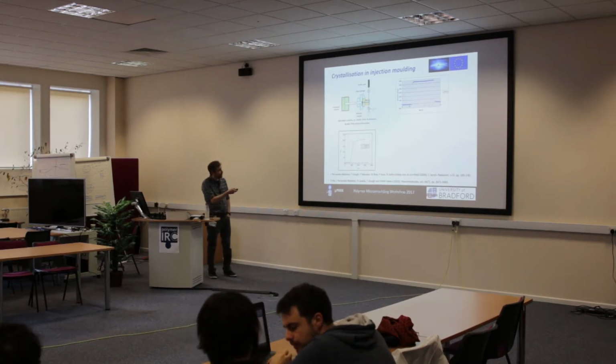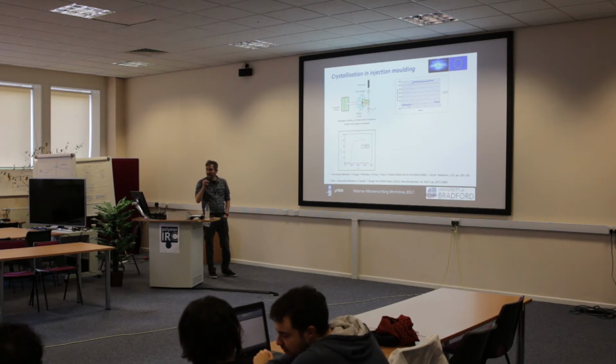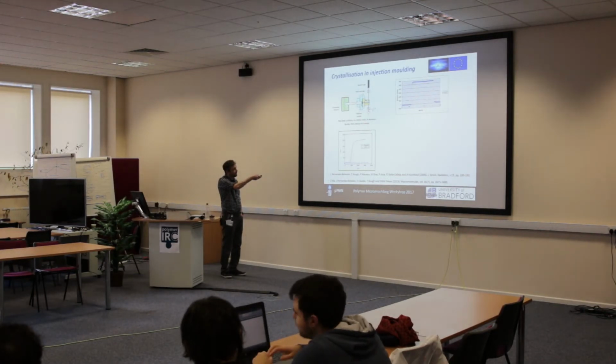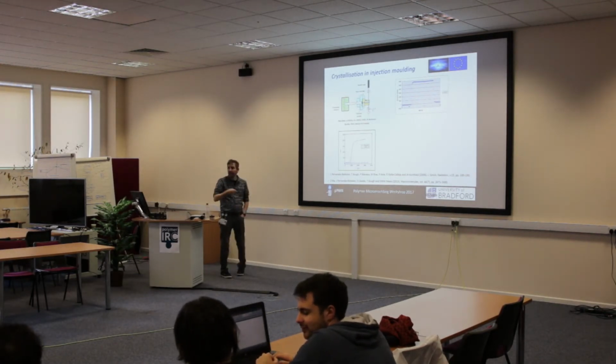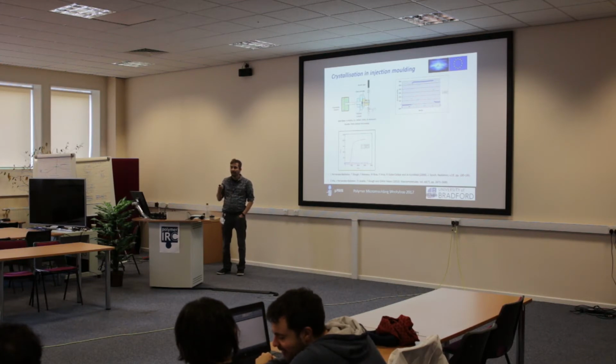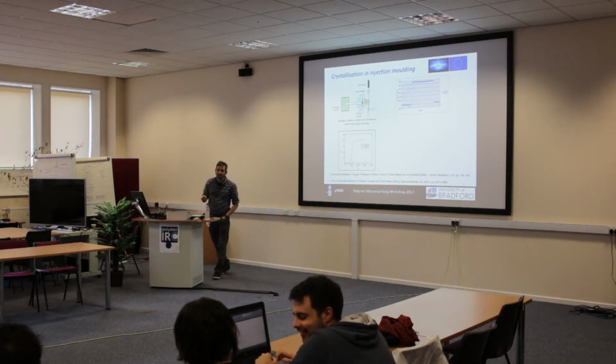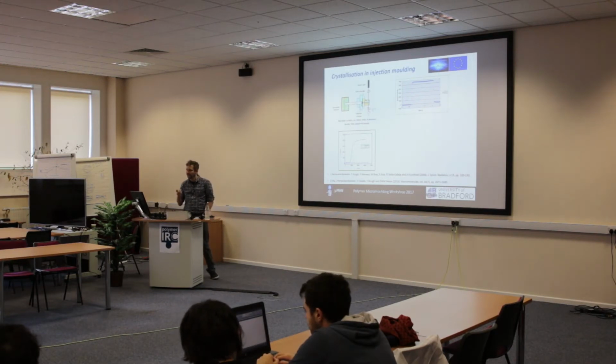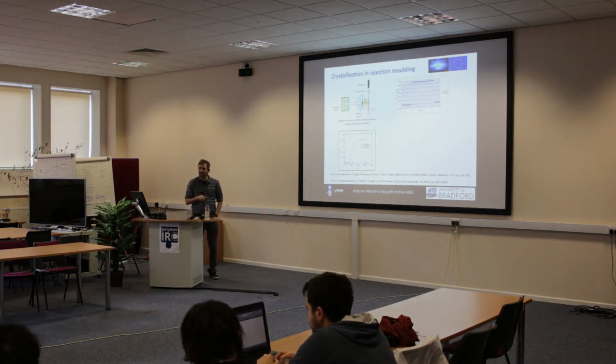By putting a pulse of energy into our material, i.e. flowing our material, this is our crystallization profile. Everything is done within a third of the time. So you can think about playing with your temperatures, your flows, and your injection speeds to give you the crystallization profile that you actually want.